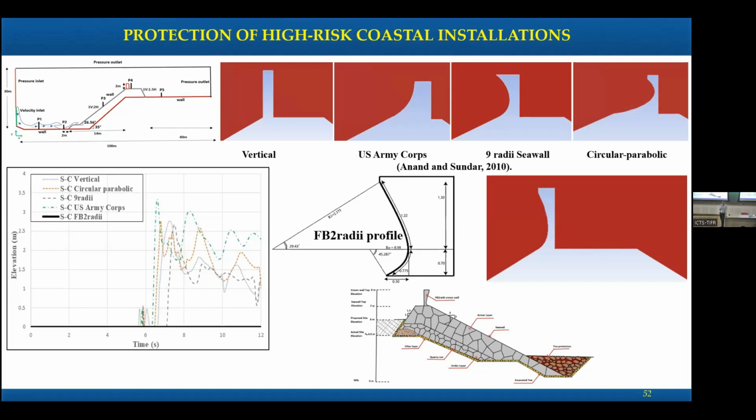Finally, we started working on that further, and we ended up getting a profile which gives us zero overtopping. That was suggested to the nuclear power body for implementation. This again requires cyclone modeling, then tsunami modeling, then finding out how overtopping happens with a sea wall, and on top of that there is a crown wall. The crown wall profile will have a curved shape.